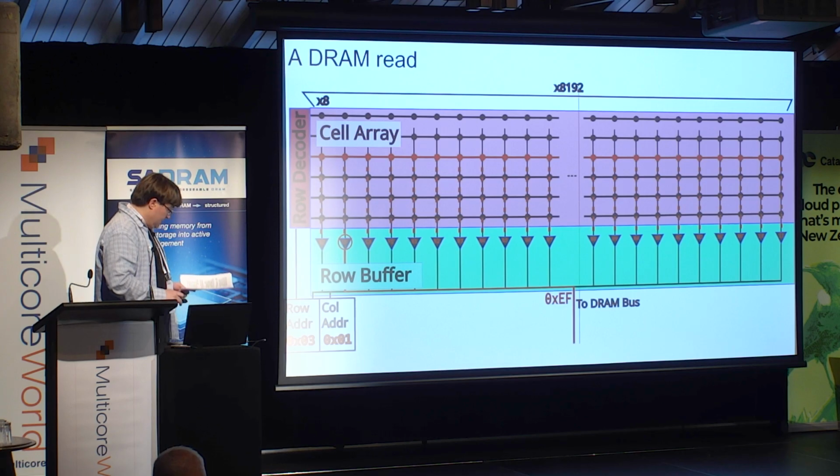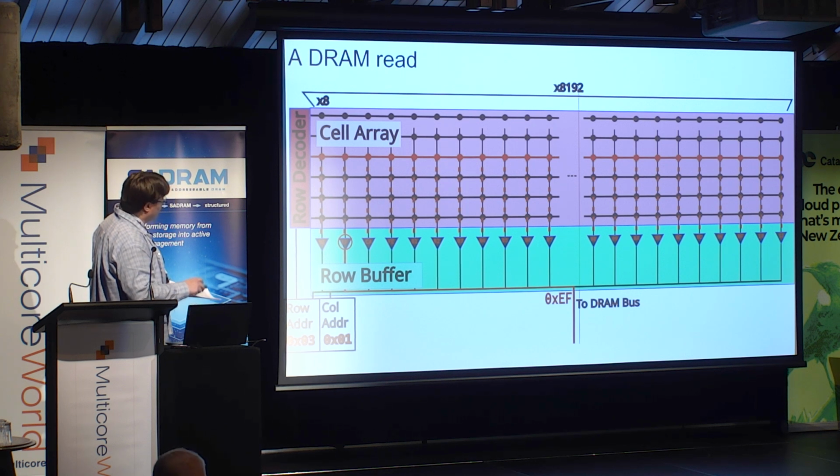All right, so when you're using DRAM, you open a row. You latch a row down here, and that picks one of these rows. We latched 3, and that's going to decode into row 0, 1, 2, 3, and then the 1T1Cs that are here are going to release their charge, which flows down these vertical lines, called the bit lines, down into the sense amps.